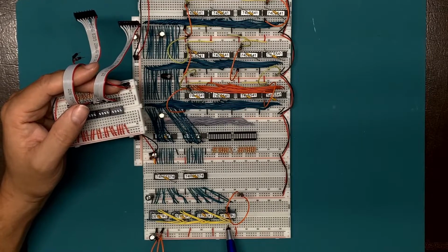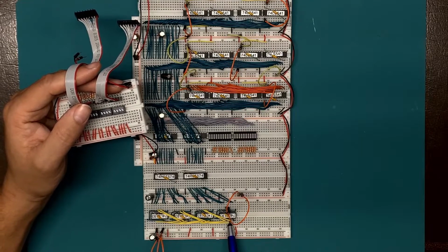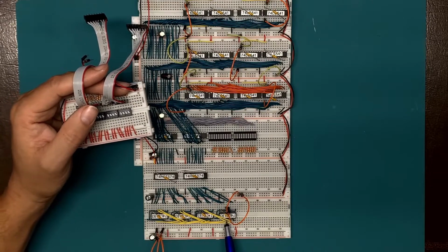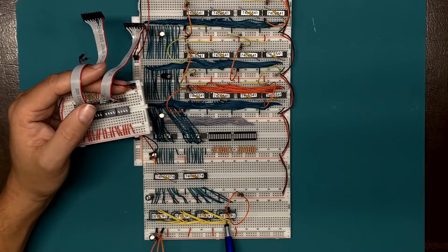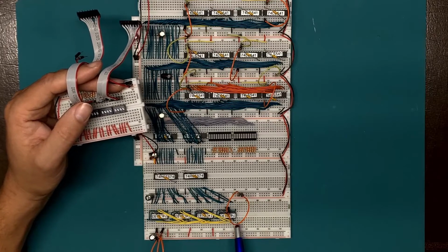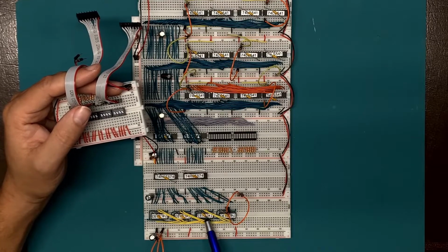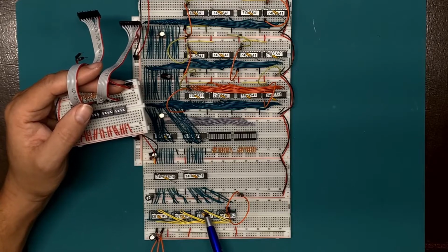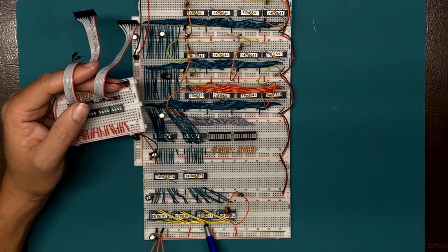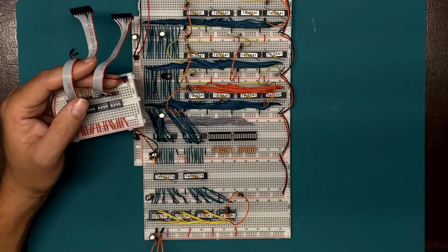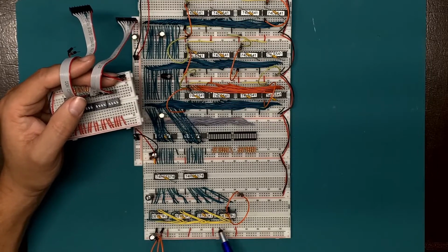And the output of the carry and borrow, I believe I have those right. Pin 13 is borrow, pin 12 is carry. So 12 is carry, 13 is borrow, are tied into the count up, count down of the next more significant nibble, so that each one of these ripples up the IC chain.